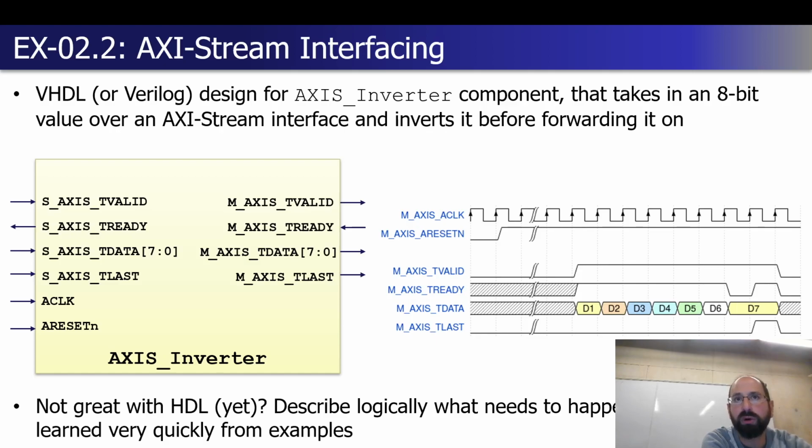A lot of the IP cores you're building are going to effectively be pass-through type components, because we have this rendering pipeline where we're receiving some input data, doing some work with it, and then generating some output data. So your cores are going to look a lot like this at a high-level interface. You are going to be a slave on the AXI stream interface because you're receiving data via that FIFO-style interface. You're going to be doing some work with it. And you're also going to be a master on a separate point-to-point interface because you're sending things downstream. You're in the middle of a pipeline, waiting for data and also sending data.